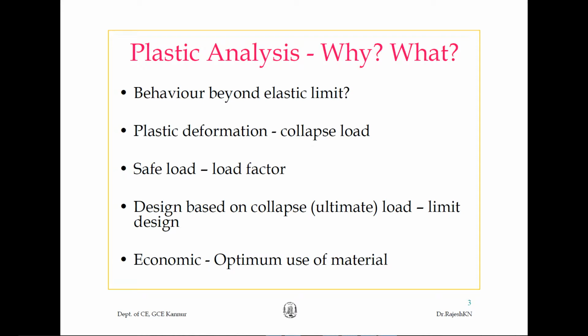And in plastic deformation, the ultimate collapse load occurs. Basically, in the elastic behavior of a material, we study up to the point of yielding, and in plastic deformation we study up to the collapse load. What are the safe loads, and what are the concepts of design based upon the ultimate load?